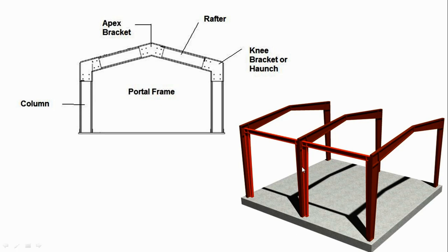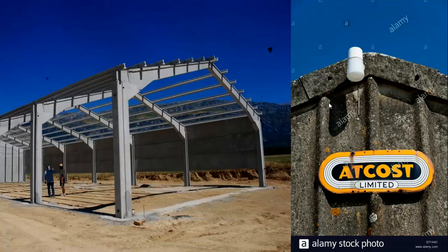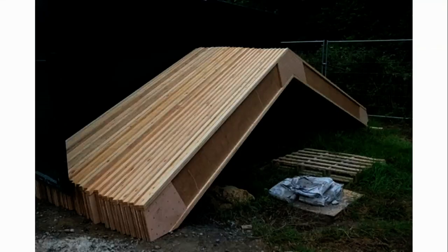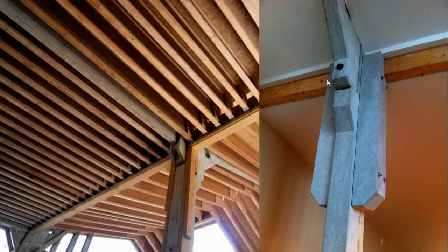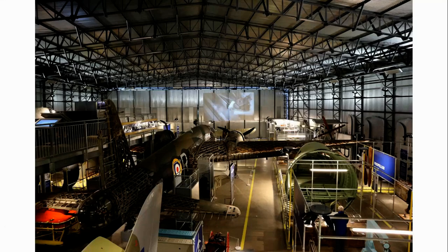There you can see literally the triangulation of the spans of the spanning elements here, can't you? And they're repeated. This is quite an old system. It used to be used for making agricultural barns, and it's concrete. It's a concrete portal frame. Very nice. There's again an engineered timber version of a portal frame. Can you see it's the depth? It's this depth in the section that's allowing it to work as a portal. There's a trussed version of the same.